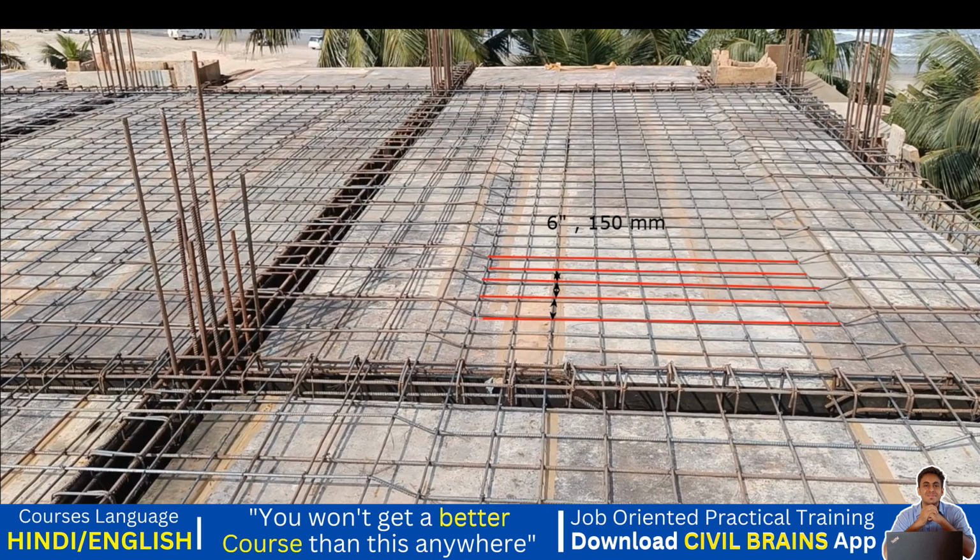See, here your bar is not continuing, whereas here your bar is continuing. Here your bar is continuing, right? But again next you don't have the bar continuing because that bar has been cranked, but this bar is going straight. Getting my point? Next this bar has been cranked, whereas this bar is continued, right? So what has happened now? Whatever spacing we were giving of 6 inches, 150 center to center spacing, near the support the spacing has got doubled. You agree with me?